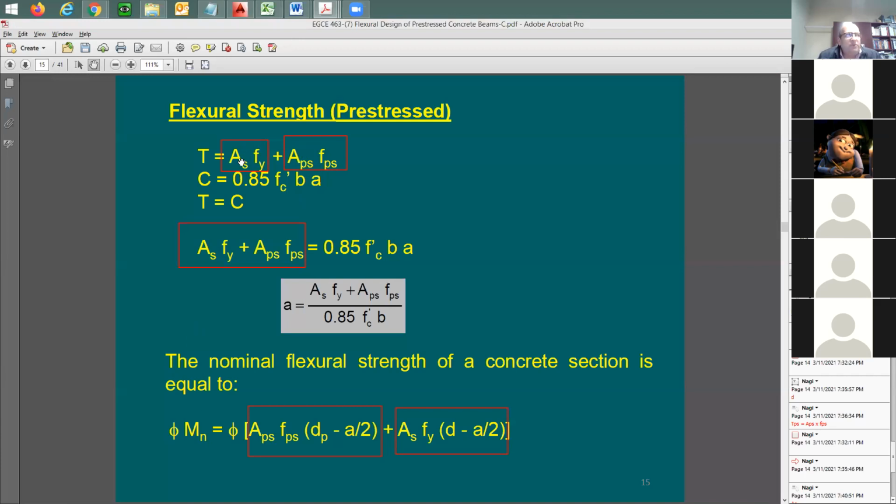So why would you use this? The answer is, this is cheaper. It doesn't need any pre-stress. And also it helps you control the cracks. When you do top and bottom, you can control the cracks. And just in case you lose the pre-stress, if something wrong is going to happen in your beam, at least you have some strength to support the beam.